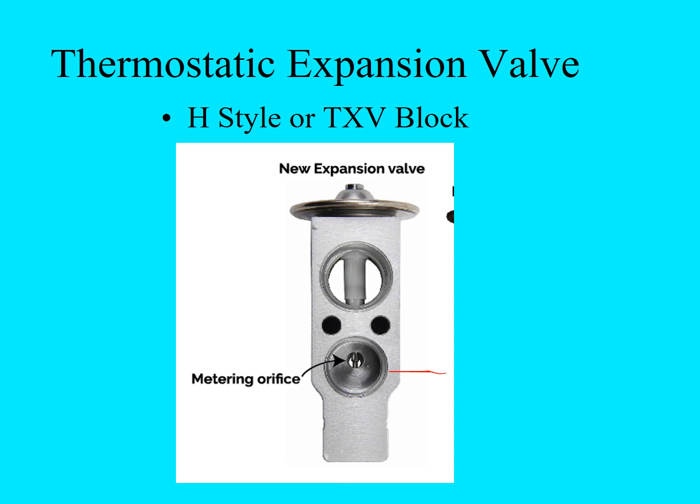This is the connection up here for the evaporator outlet, which would be low pressure, low temperature vapor flowing right across this little section here. This is basically the sensing bulb that's hooked to the diaphragm at the top that's going to make the change down here at the metering valve right at the bottom.